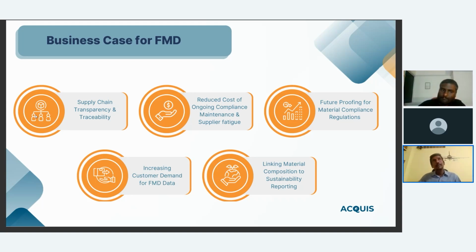So knowing the complete breakdown and the substances, having that substance-level control of your compliance program, helps you have transparency within your supply chain, and also traceability. If somebody is claiming that they are using lead in some use case and claiming some exemption for RoHS, you will know where this substance is used and cross-verify whether the exemption is suitable for this application, or whether the supplier has wrongly claimed the exemption.